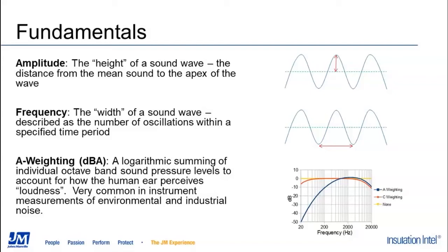We get a little more into that detail with our third point here with A-weighting. A-weighting is an interesting concept, and we have a graph at the bottom right-hand side of your screen that kind of describes A-weighting in a graphical sense. What it basically is, it's describing the relevant sounds that our ears can pick up as people. A-weighting is describing the basic curve between the frequency range that we've discussed before, from low frequencies to high frequencies. There are certain levels of sound and certain strengths of that sound that our ears will naturally pick up, just dependent on that frequency.